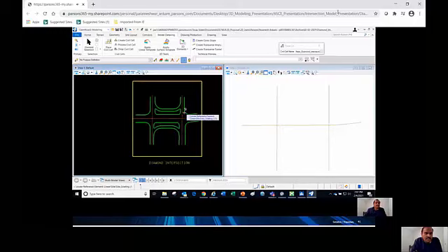With just a few clicks, it can develop a very detailed intersection model for a diamond intersection. This civil cell generates a 3D model for half of the diamond intersection, and then the same cell can be used to develop the other half of the intersection.